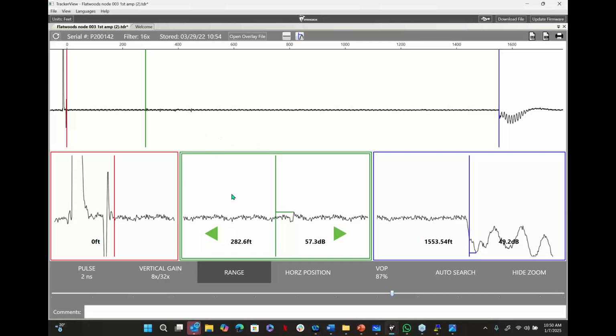So as I'm looking at this a little bit further, this is the first thing that I was wondering. This is goofy to me. Look at the pattern. I'm wondering, is it possible that these are ghost reflections? And by the way, I don't think they're ghost reflections, but let me tell you why. Ghost reflections tend to happen the most at greater distances, but these look like they're so close to exactly the same distance apart.